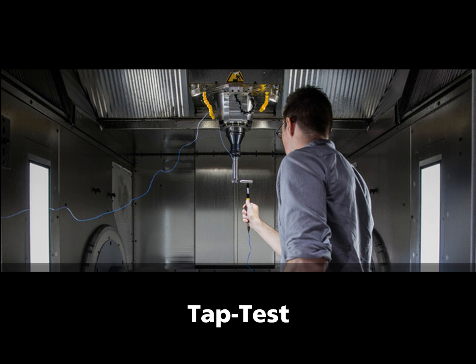calculator. Note that you do not necessarily need to perform these tool and material characteristic tests on the same machine as your customers or even with the same tool holder. The resulting cutting stiffness and process damping values can be applied to future tap tests of the same geometry cutter, even of different diameter and lengths, in the same material. Also, a very short end mill and a short tool holder may not produce discernible red zones required for this testing. Use a longer version of the geometry tool and or a longer tool holder.